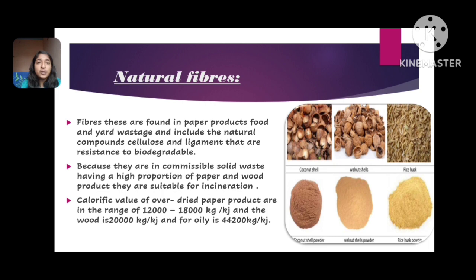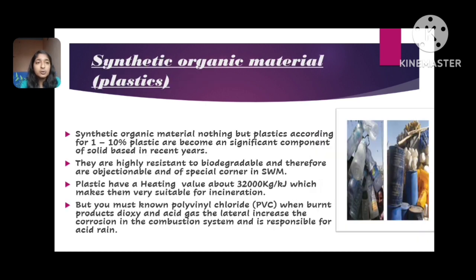The next is natural fibers. These are found in paper products, food and yard waste, and include natural compounds such as cellulose and lignin, which are resistant to biodegradation. Because they are combustible, solid waste having a high proportion of paper and wood products is suitable for incineration. The heating value of dried paper products ranges from 12,000 to 18,000 kilojoules per kg, and wood is 20,000 to 44,200 kilojoules per kg.